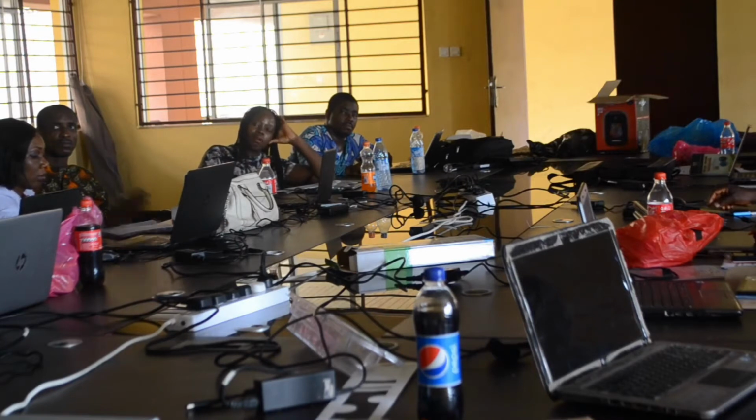You have everything, your menus like this. For Autodesk Moldflow injection plastic, your left-hand pin is where you have your parts. The parts are there. Then you have your injection, where you place it. When you click on the injection icon and begin to pick places where you want to put the injection, it will appear. Are you getting it? That's part of the list.